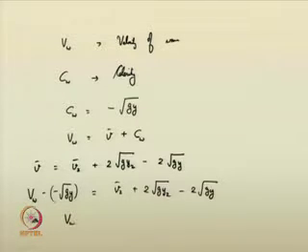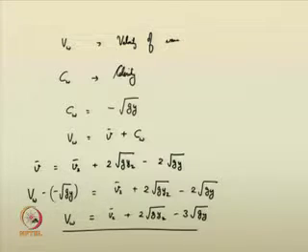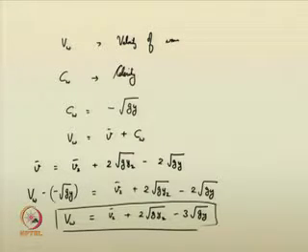The velocity of wave at any section, which is the important thing we require here, is nothing but equal to V2 plus twice root g y2 minus thrice root g y. Like this I can derive the expression for velocity of wave at any section.